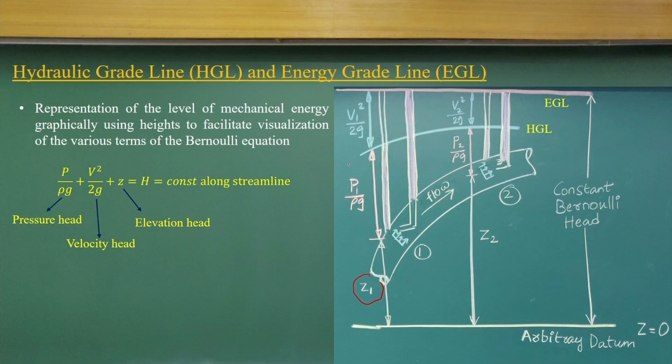That means, if I have a liquid, how much it will lift because of the pressure, the flow energy, the kinetic energy and the potential. That is the reason we define it as head: the pressure head, velocity head and elevation head. There is nothing else; they are all three energies, flow energy, kinetic energy and potential energy, constant along a streamline.